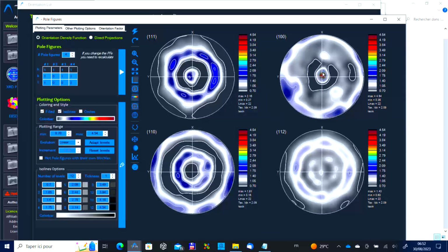A copper bar, which was extruded, a circular bar, extruded with a circular die, and obtained. So this is why the sample symmetry somehow is appearing in the texture. So the z-axis, because here the z is in the middle, you see, and around this axis we see these circles. So the z-axis is a circular symmetry axis.